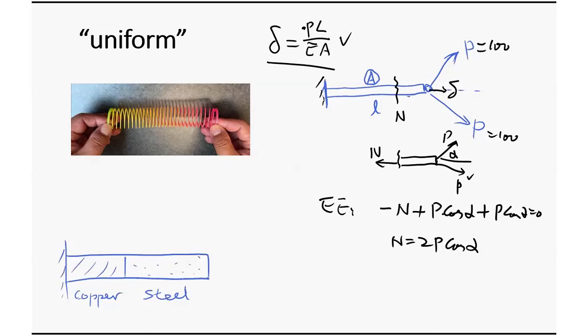For this reason, I want to remind you, when you use this equation, the force in the equation should be the actual force in the bar. It's not what they gave there, like in this situation, they give you 2P. You cannot just use the P there, right?